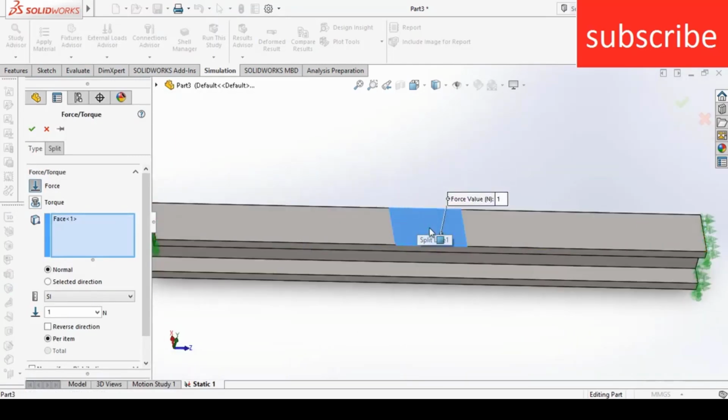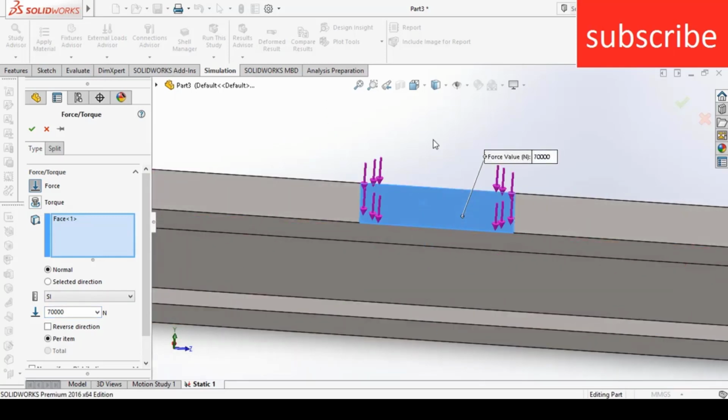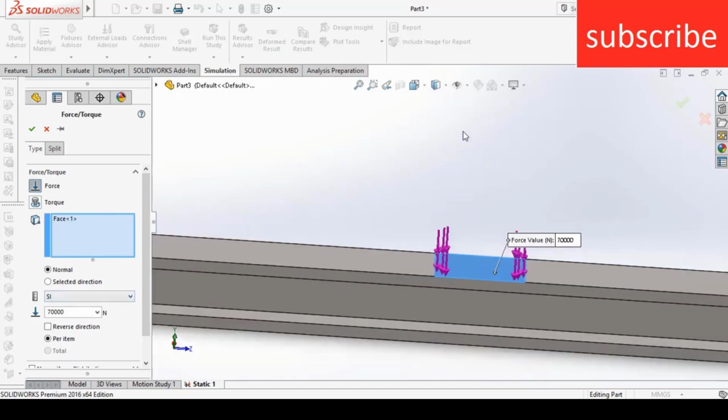Before that I was selecting this whole beam, but I don't want that, I just want my load to act on here. So enter the value of 70,000 Newton, or you can change the value as per your requirement, and make sure the arrow is acting in the downward direction, because my load is acting in the y direction downwards, not upward. If somebody says my load is acting upward, just click on reverse. As you can see the load is acting upward, but in my scenario the load is acting downward.